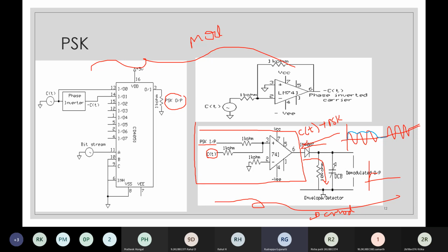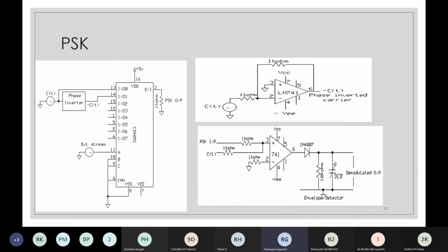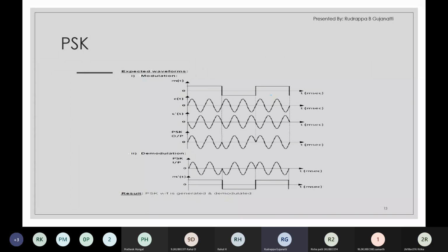So during the entire time when the bit is 0, when nothing is there, it becomes 0. So again this charging and discharging process continues, and we'll be having a waveform which will be of this kind. So now what we do is, in this given bit interval, we can observe that bit is 1, and in this given bit interval, bit is 0, again bit is 1 and bit is 0. So this is the demodulation with respect to PSK implementation. So this is another example what we have taken. So we try to recover the original information.